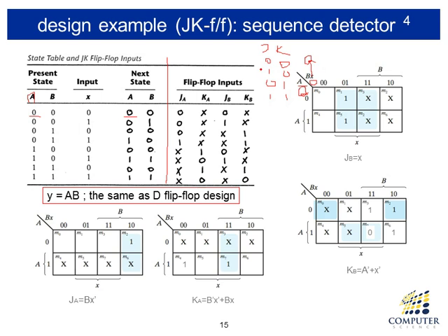0, 0 remains unchanged. So this is the behavior of a JK flip-flop. On the first entry of the state table, flip-flop A remains unchanged with a 0 value. Then how do we apply JK input for that? To have output 0 on the next clock tick, we will have 0, 1 as JK. So 0, 1 is one choice to make output 0 on the next clock tick.